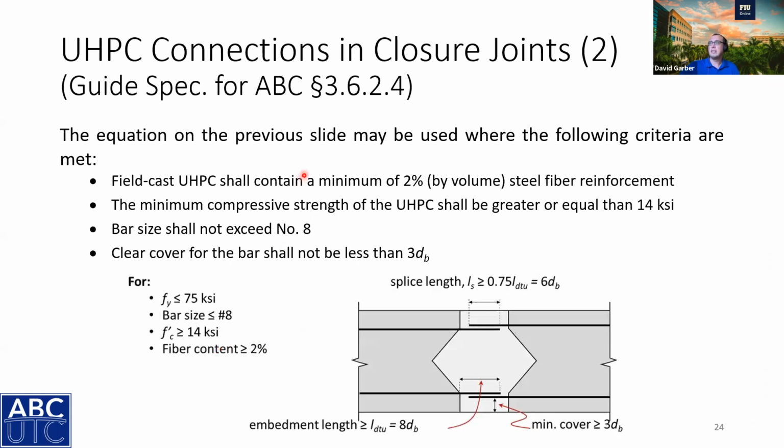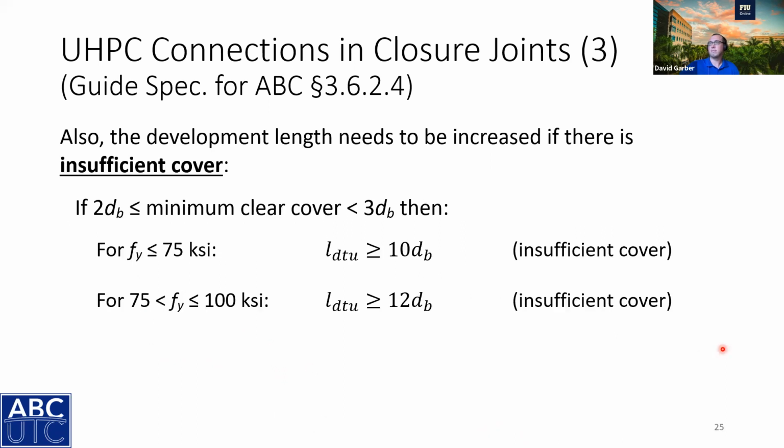Here are some of the criteria for that, or further requirements I showed on the previous slide. So, what bar size, what concrete strength, fiber content, and what the detail actually looks like. There's a requirement for minimum cover. So I highlight that here.